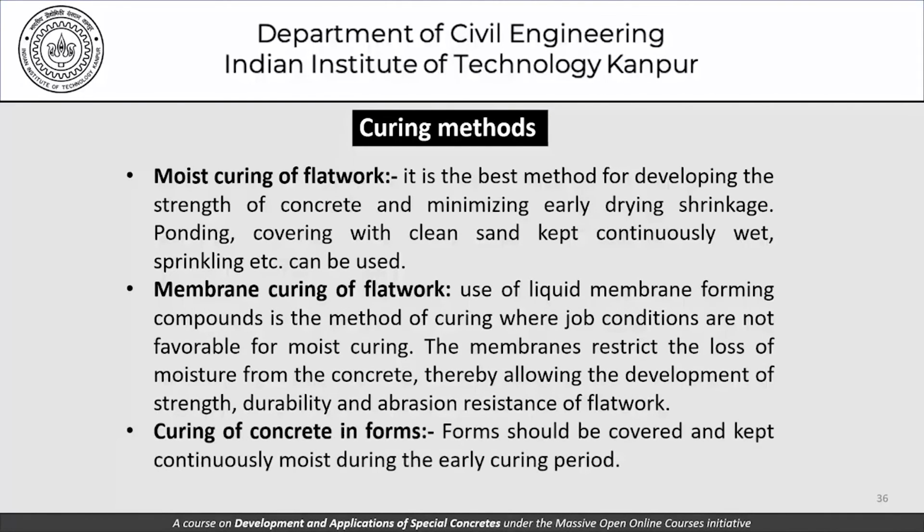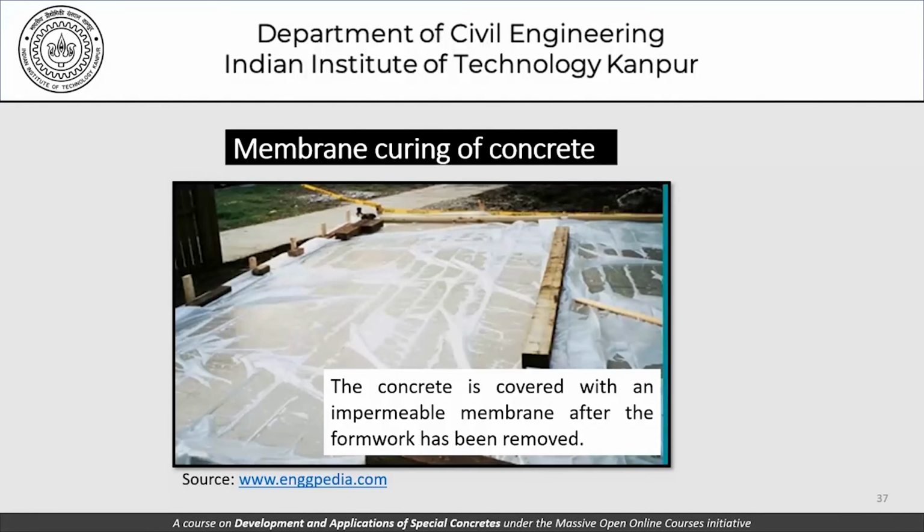Curing of concrete in forms. One option that you have is that forms should be covered and kept continuously moist during the early curing period, rather than removing the forms and exposing the concrete directly to the higher temperatures. Membrane curing, as we can see here, concrete is covered with an impermeable membrane after the formwork has been removed.